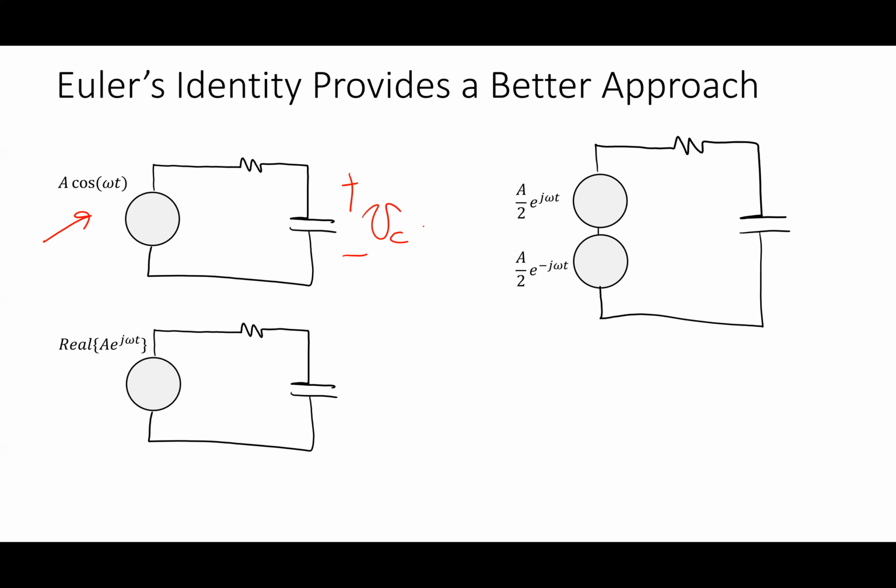It's what? Low pass filter. Yeah, you got the key part. In other words, what this guy is, is a low pass filter. We're going to talk about what that means, but this filters low frequencies and gets rid of high frequencies. That's a good thing when I'm sampling signals, when I'm hooking things up to microcontrollers. We'll talk about that more, but suffice it to say this is a pretty common circuit because of what powerful stuff it enables us to do. All three of these circuits are equivalent to each other.